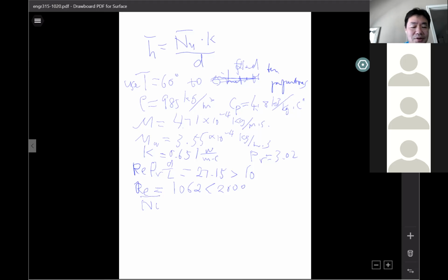Okay, for the isothermal condition, the Nusselt number is 5.816. Notice if it's iso heat flux condition, there's a constant Nusselt number. Do you remember what is that value? I don't think it's 5. I think it's 4 point something, right? 4.364. That's for the iso heat flux.